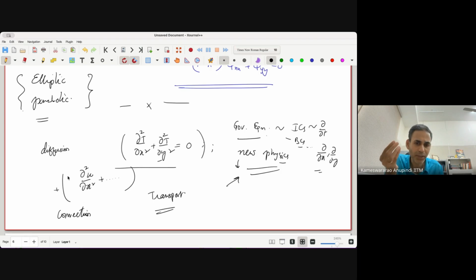I think the best way is to compare with the existing set of equations that we know from continuum mechanics or continuum fluid mechanics, right? You have convection diffusion, you have the Navier-Stokes equation, you have the species transport equation, you have the energy equation, or you have equations in solid mechanics. First, we have to draw some kind of similarity or analogy to the existing set of equations.